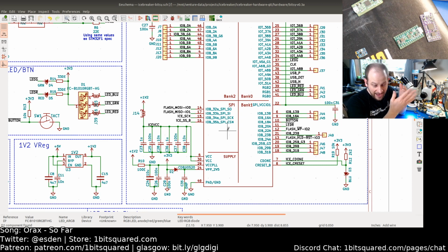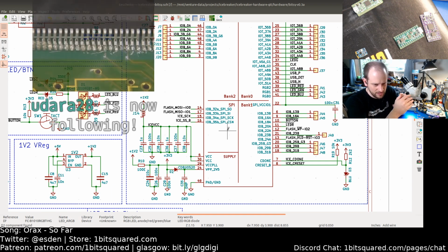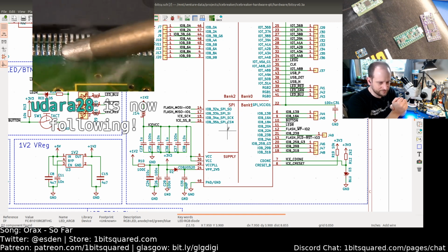And the iCE40 UP5K also has more fuse bits. Again, that's a rumor. That is big enough that you can fuse a few bitstreams before you run out of fuses. That's not documented, but I heard from a few people that this is the case, and you could fuse new streams a few times.